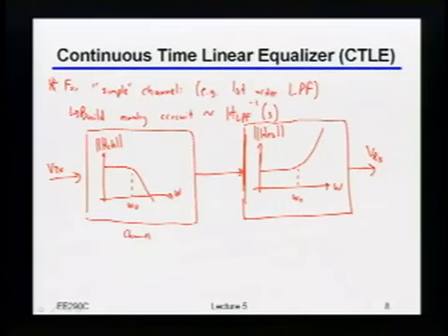Yeah? There's phase distortion. Okay, well that's fair. But I guess my intent was really to take H inverse like in the S domain. So whatever the S transfer function was for the first one, I'm literally going to try and do the inverse of that for the second one. So that would take care of the phase distortion too. I mean, you can't have that going up with frequency. Okay, so why not? Why can't I just have this keep going up like this?